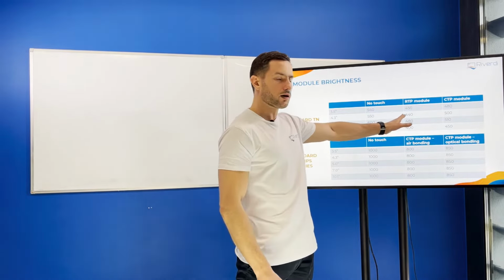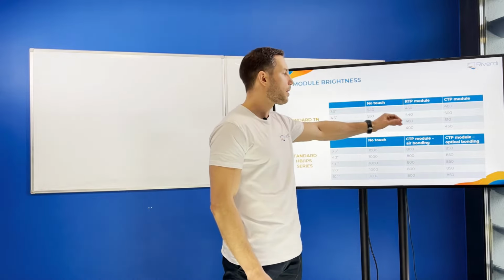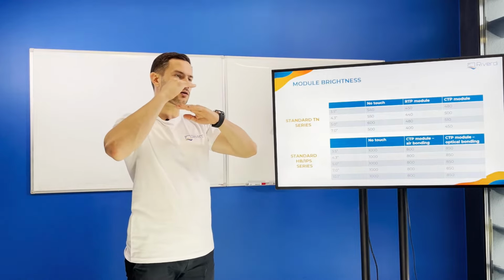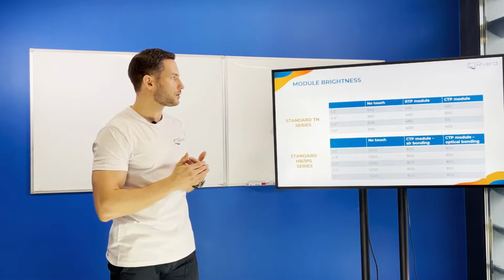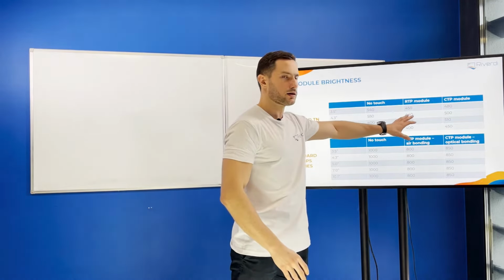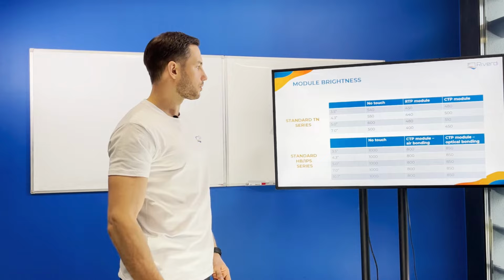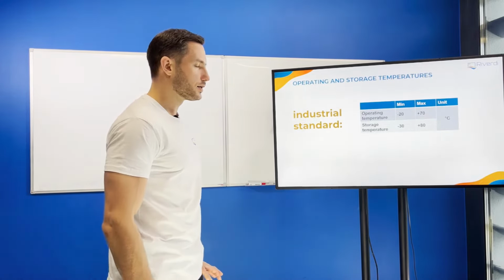Here we also have, in the old generation line, cooperation with the resistive touch, and because resistive touch includes more layers, we have another air gap, which is necessary for us to press, because resistive needs to be mechanically pressed. We have even lower brightness because there are more reflections than with typical pickup without optical bonding. So just a reminder, this slide.